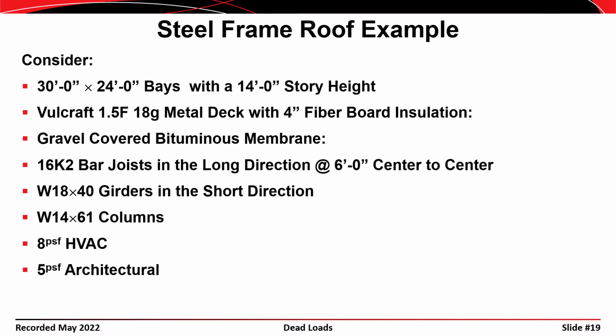And our HVAC load is a little less. Instead of 12 PSF, we'll take it as 8 PSF. And the architectural is also going to be lower. Instead of 15 pounds per square foot, we'll take it as 5 pounds per square foot, because the roof would be supporting a ceiling below it, but presumably would not be supporting any flooring above it.